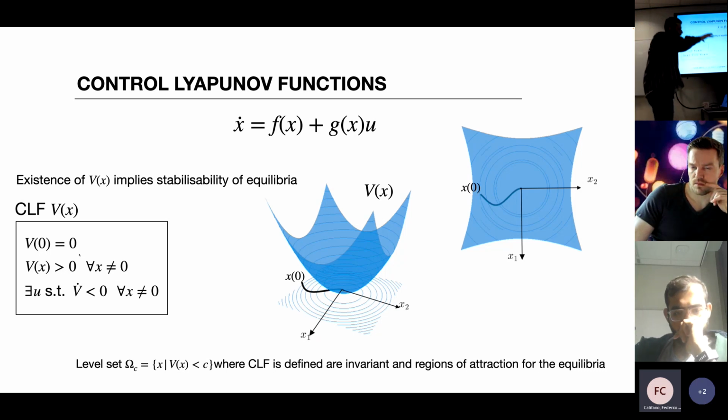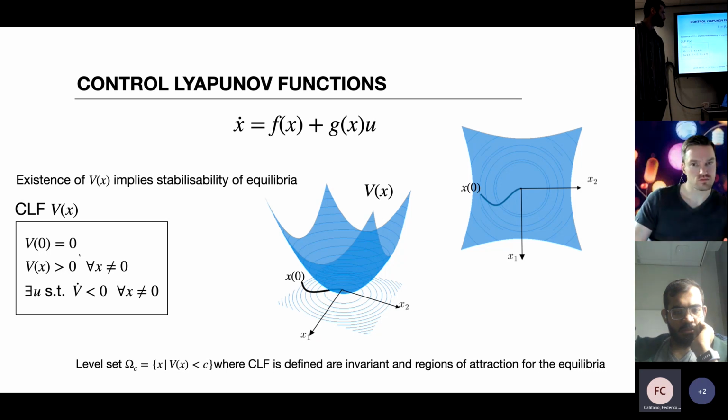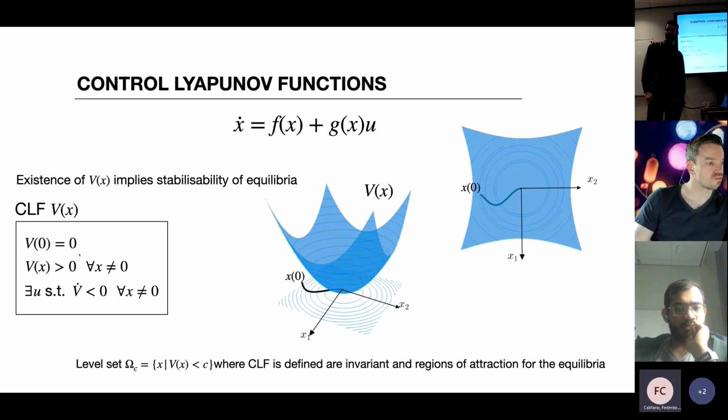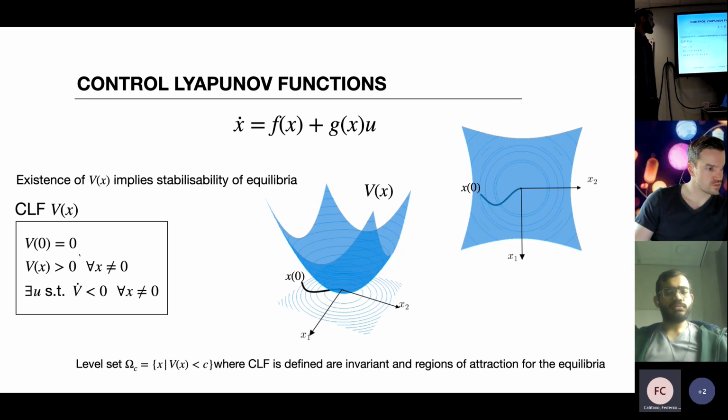But say we have an input of the system, we can control something, so we have a degree of freedom on the dynamics of the system, and let's suppose that the system is affine in the input. What does it mean? That the input enters linearly, through some kind of input matrix G(x), some kind of input vector field. So again, suppose the task is that by means of control, we want to stabilize a system, an equilibrium or a set, and so on.